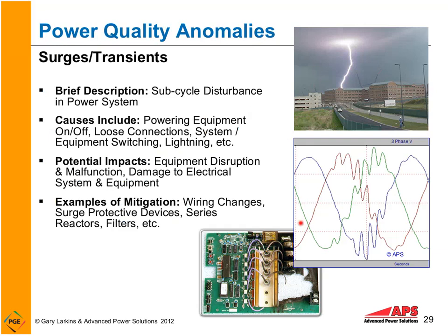And we can see here, this is a transient right here, or power surge, some people call it. Okay, and this was actually caused by power factor correction capacitors switching on in the system. And this is an example of the power factor correction capacitors that were actually causing those escalators to trip at that airport I mentioned. So whether we have load switching, in other words, we start up a large load, it can create a transient. We have lightning hits a line, it can create a transient. Loose connections. We should have adequate surge suppression installed on our system